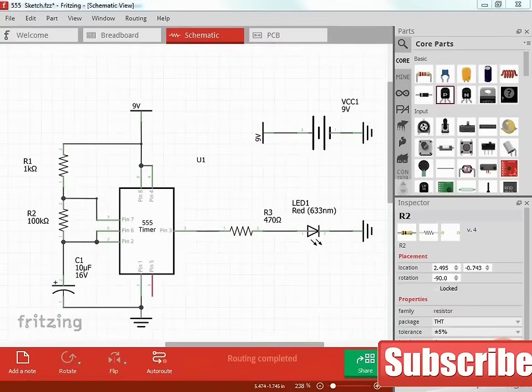We can see that everything that is connected in the circuit, although it's not physically connected on the drawing, that's marked 9 volts, is electrically connected, and also with all the ground connections. We have 2 9-volt connections and 3 ground connections. This is a way that we can clean up our schematics without having lines drawing all over the place. We just put symbols for common connections, and we assume that they are all connected electrically.